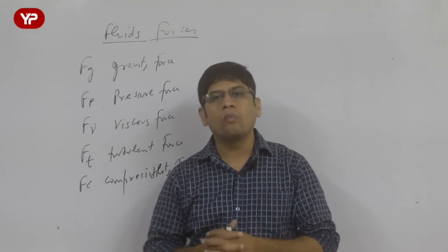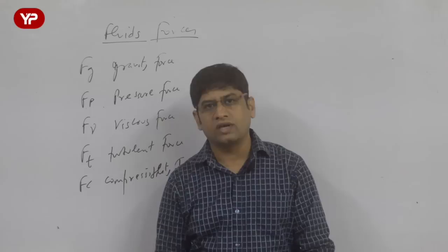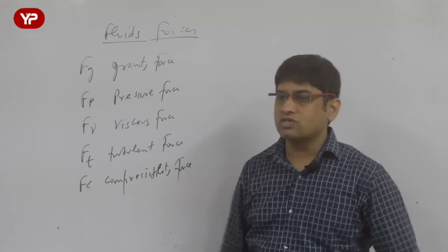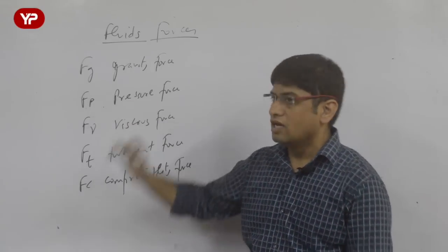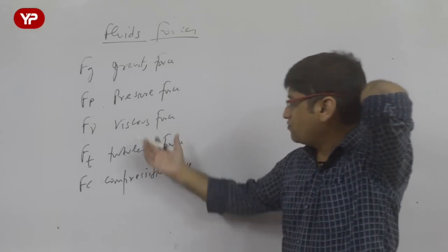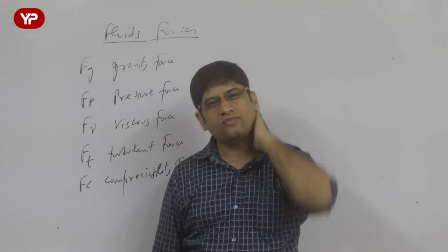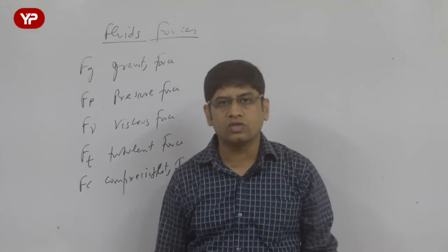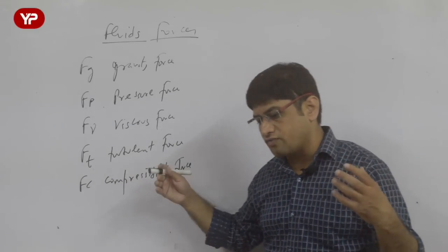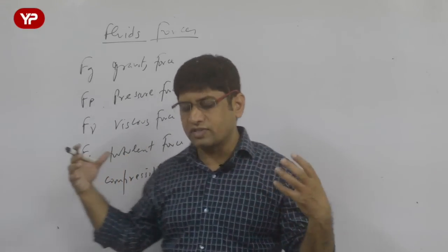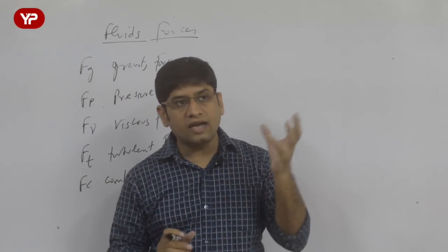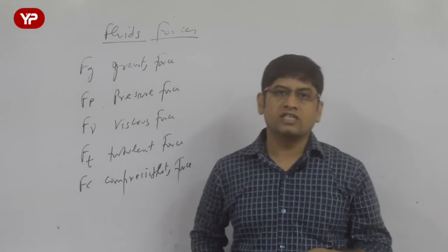Like I told you, open channel flow, or fluids flowing in a river or canal, these are all gravity forces. These are significant forces. Similarly, in case of pipes, the force which is significant is the pressure force. Viscous force is significant when viscosity is more; normally it is a resistance or friction force. Then turbulent force: when the effect of viscosity decreases, then the effect of turbulence or mixing increases, and in that situation the turbulence effect is more.